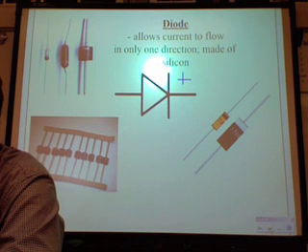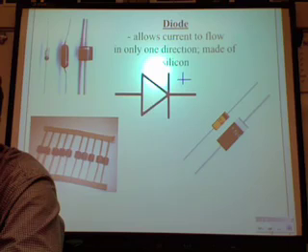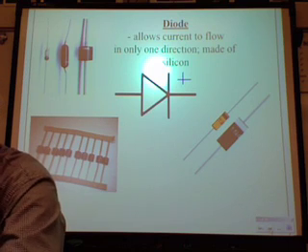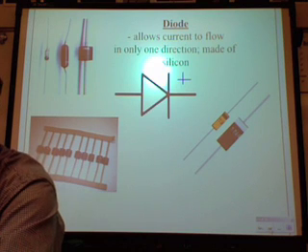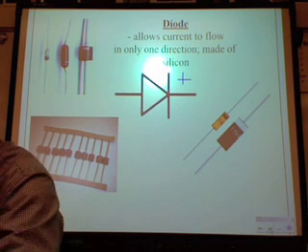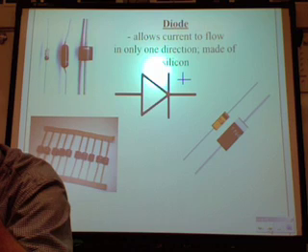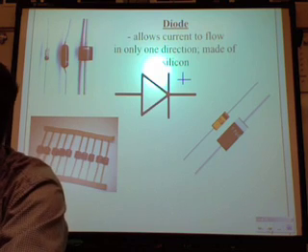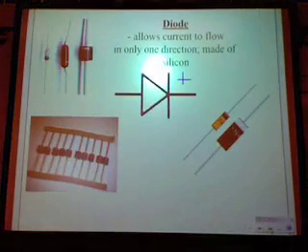No, this is something found inside the AC adapter. AC adapters include something else as well as this. The thing that turns AC to DC. I told you it was basically 4 of these diodes in a package. It fixes the situation. Say it again. Close enough. Rectifier. A rectifier is 4 diodes working together.